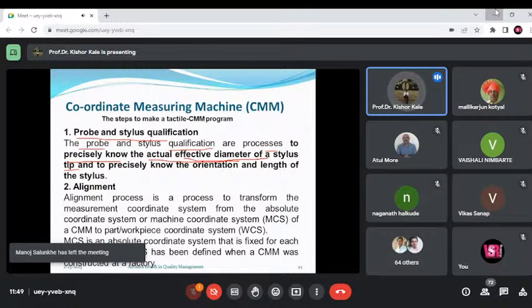So this was the part on the coordinate measuring machine. In the later part, we will go to the second part, that is the 3D scanner. This is also called a non-contact type of scanner. There is no contact between the measuring machine and the product. So you can see over here, the camera is there, the laser is there. These lasers are being pointed on the target object. You can see the XYZ is defined. It will rotate on the turntable, and all this shape will be recorded in the form of cloud data.